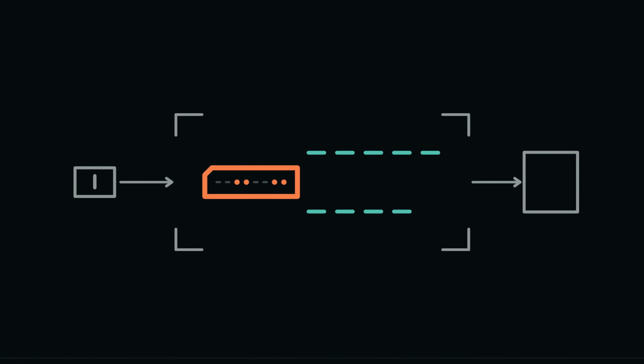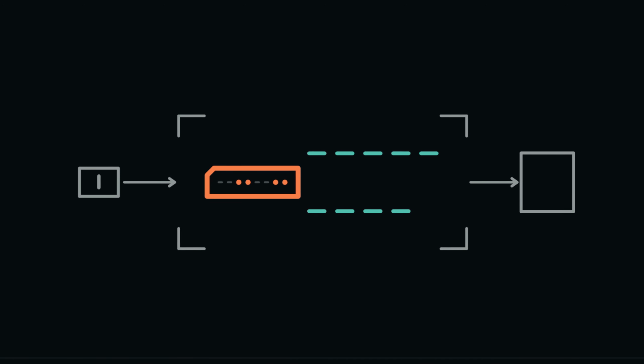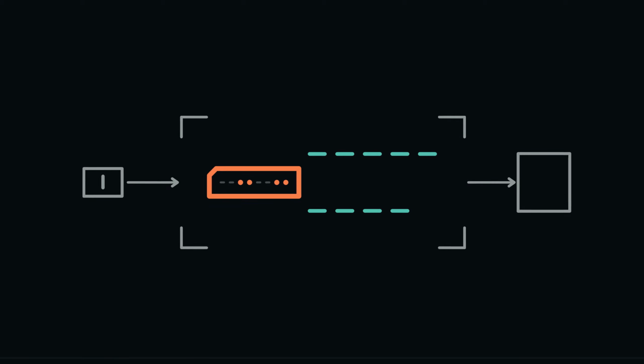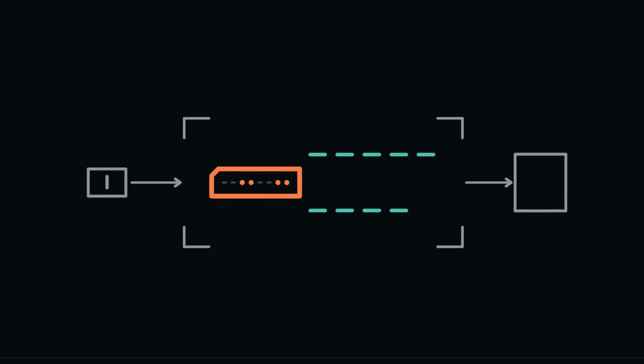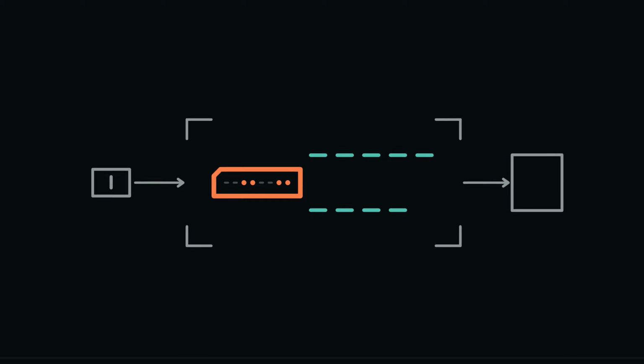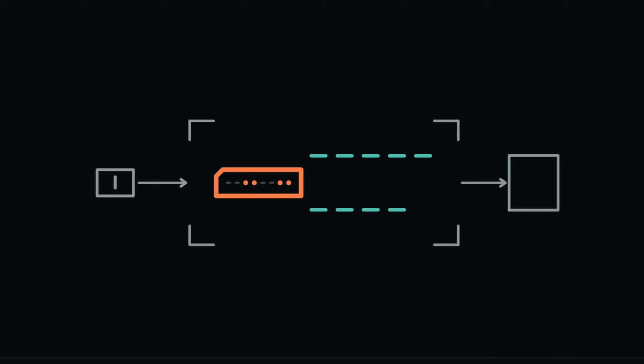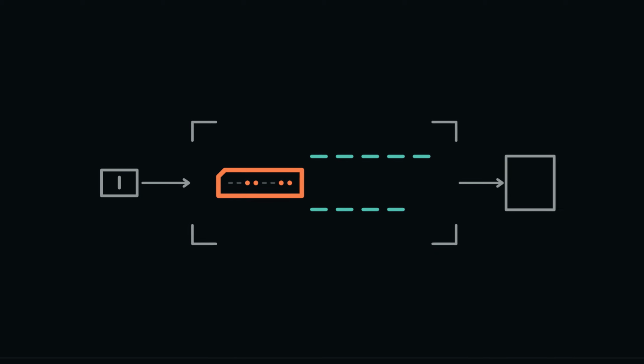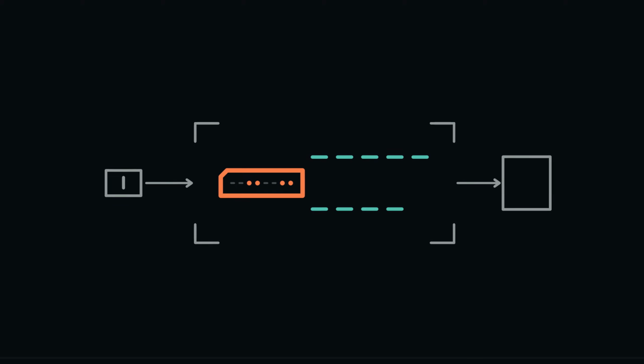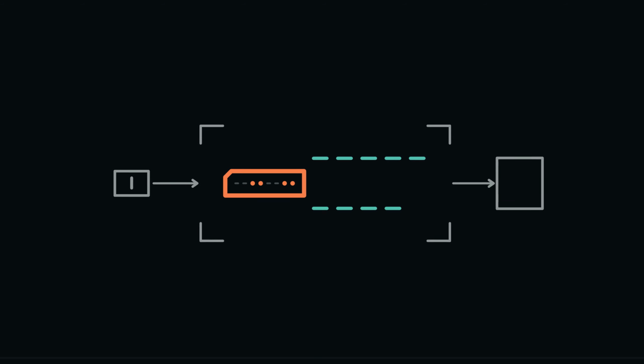A microphone voltage can vary through a continuous range as sound changes. To represent that signal with numbers, a system must answer two separate questions. At which moments will it measure, and which numeric level will stand for each measured amplitude? Keep time on the horizontal axis and amplitude on the vertical axis. Without both axes, sampling and quantization are too easily mistaken for the same operation.